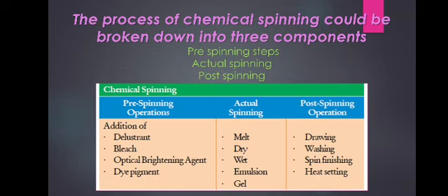As previously we said, it is formed into a solution, then it is dissolved in a chemical bath to form a solution. This solution is passed through an acid or basic bath based on the chemical substance extruded, and in contact with the bath, the solution from the spinneret solidifies and forms into a yarn. So it is known as the wet spinning process.